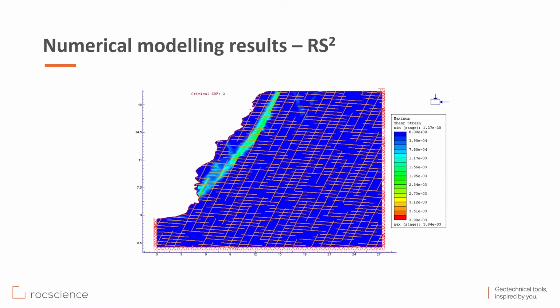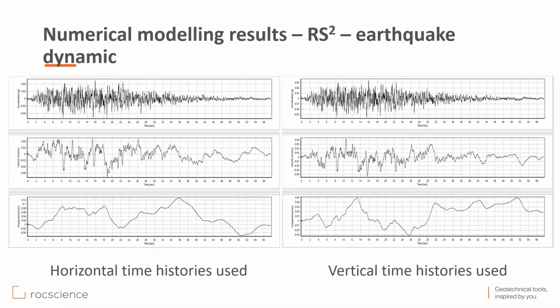Since that is not the focus of our presentation, I will not go into details, but once the model has been constructed, the shear strengths of all the component materials are iteratively increased or decreased by a strength reduction factor until the slope fails. So we used the SRF solution, and we had stable slopes during the static work.